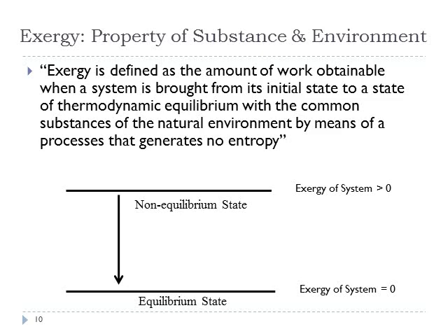Now, the trick, of course, is that if we lived in a world with no irreversibility, we'd all be at the equilibrium state. So it's this kind of ideal exergy. It's what we could hope for, but can't ever really get. We just can't get that amount of work, because any real process is going to have internal generation of entropy.